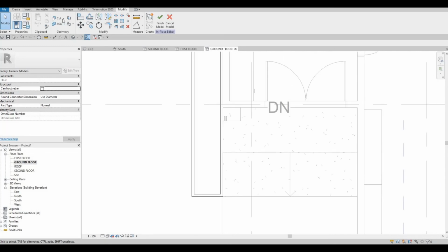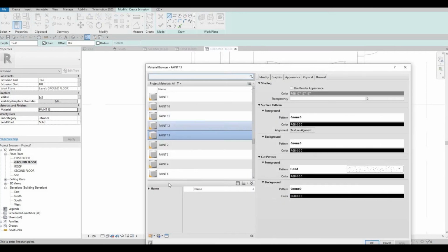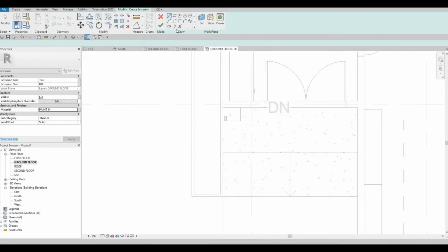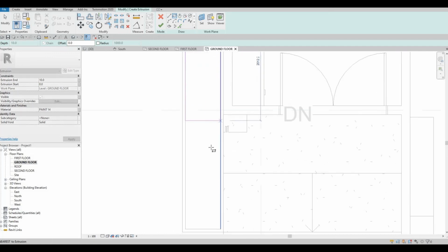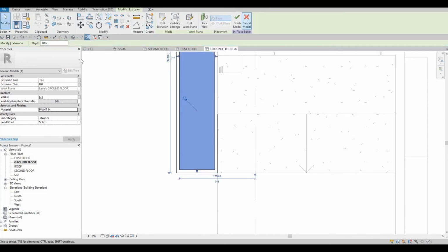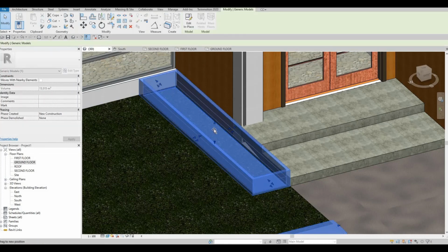And then let's add in something at the top there. So another extrusion. Let's just duplicate this. This will be 14. Apply, OK. And then create it from the inside right here. Click finish, and then finish, because we can always just select that and then increase the height.